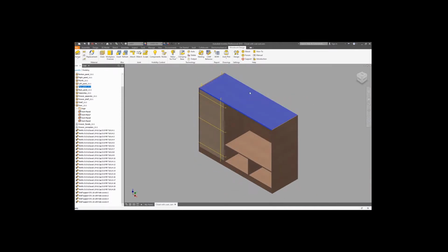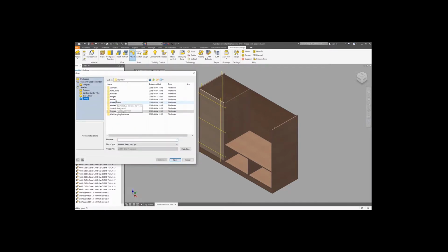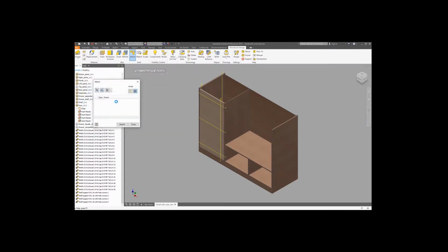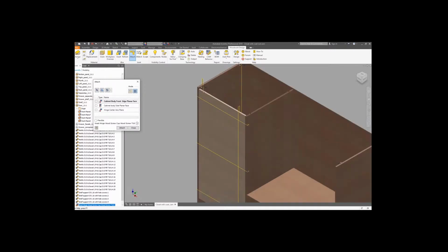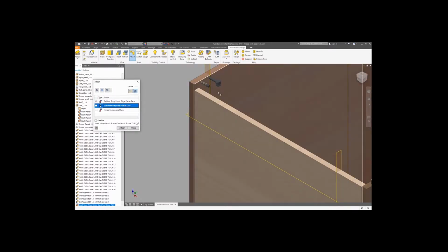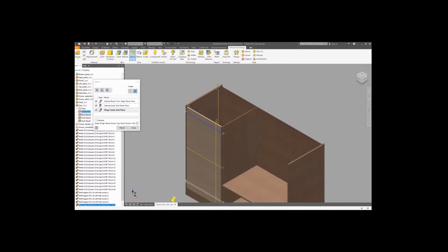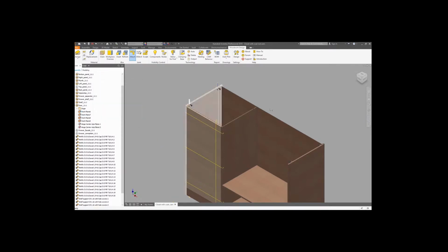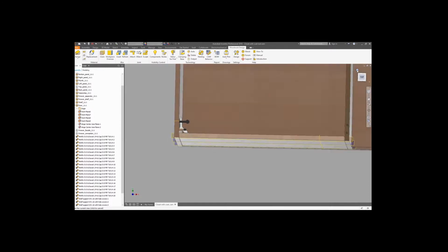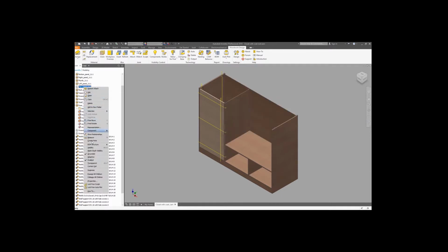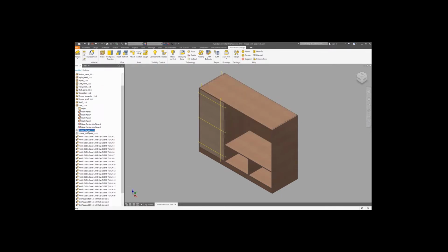Okay. Just hide the top and then use attach. In this case, from the library we'll pick the hinges, concealed hinge, insert type, okay, and then we'll choose the front of the door, side, and the hinge center axis. So remember, we have 2 hinges, but you can have more than that. Just apply some additional work planes if you need to, and that's it. The hinge is in place already. So we can make the top visible again.